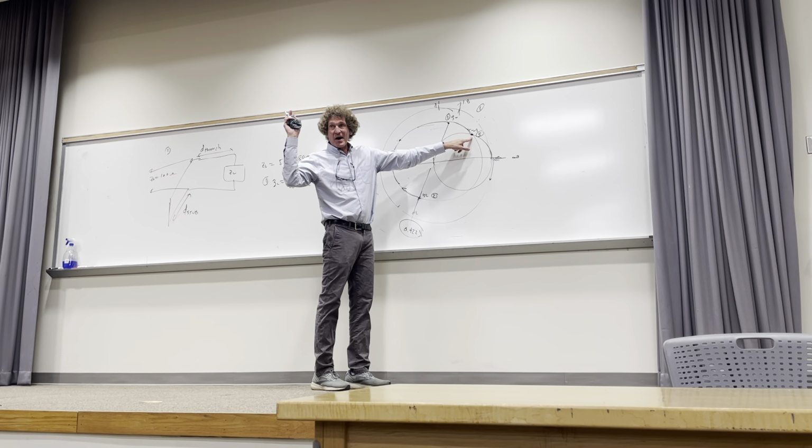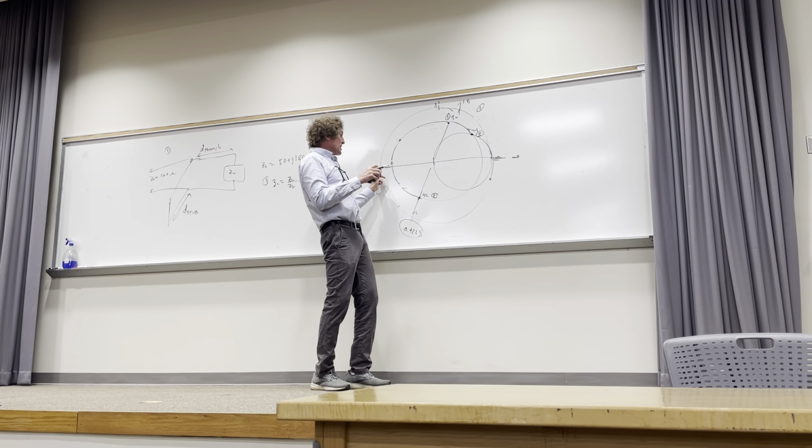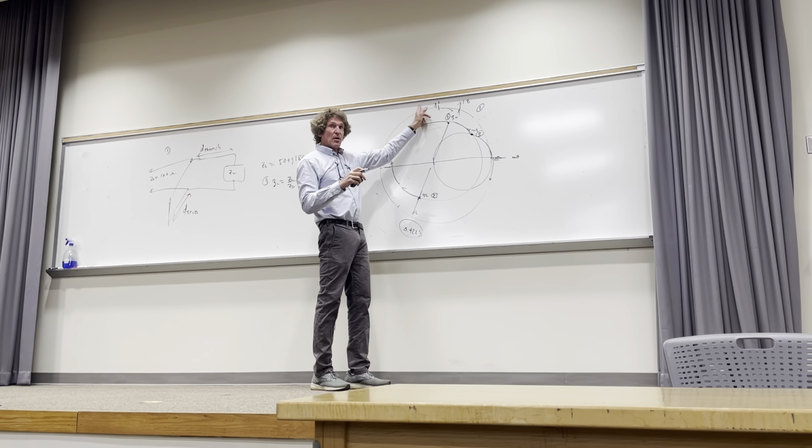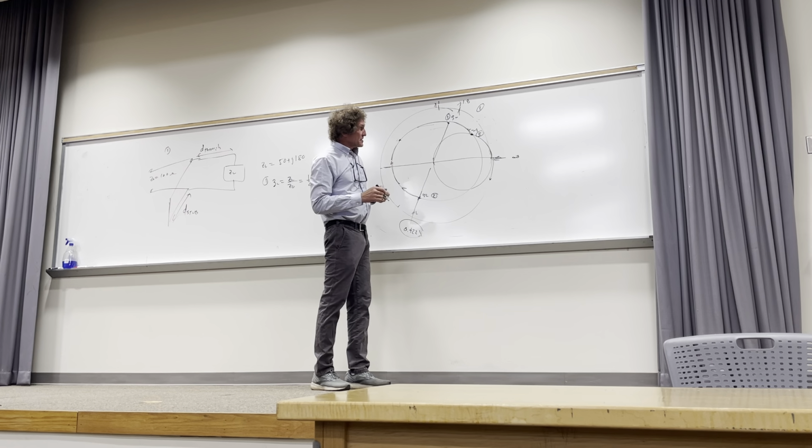Now, on the final, I could say something different, where I could say it's an open circuit stub, and then you'd want to hit this point. Y'all follow me? Because then you would want a negative J something to get rid of, because if it's an open circuit stub, it starts here, and the first values here are all positive on the ring. Y'all with me? Okay, getting back to this problem.